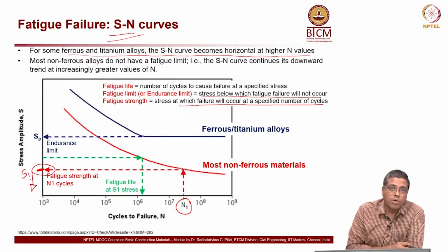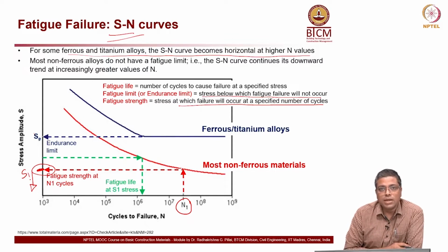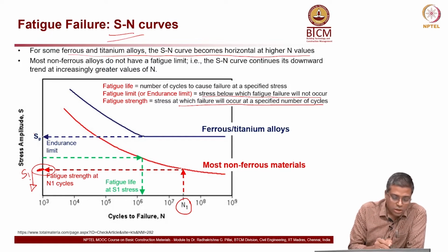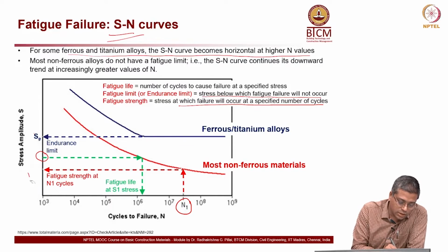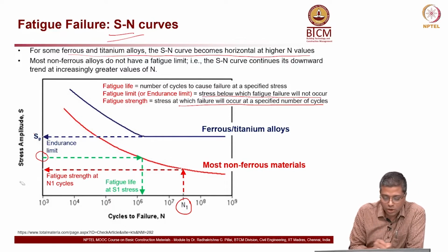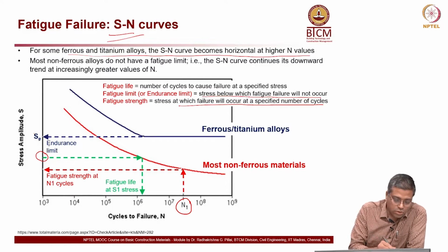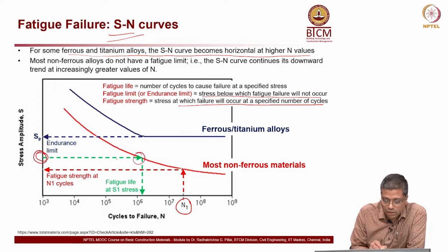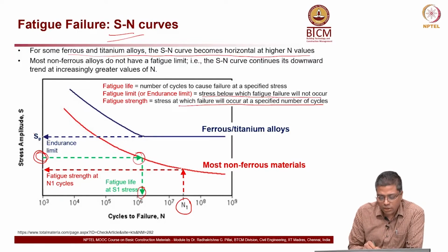Now, let us say you are talking about a bridge or any structure which is already built, and you want to see, maybe there is an increase in the load or something. So, you want to assess the remaining life of the structure. You know the stress which is applied, that is known. In the green case here, the stress is known, and I look at the change in the direction of the arrows. Okay. So, you go from here to the right and hit the curve and then come down. That is about 10 to the power of 6